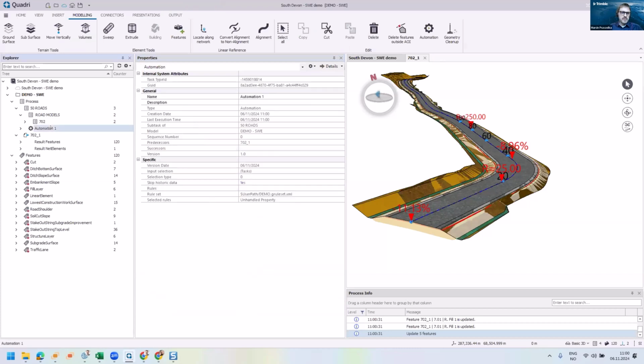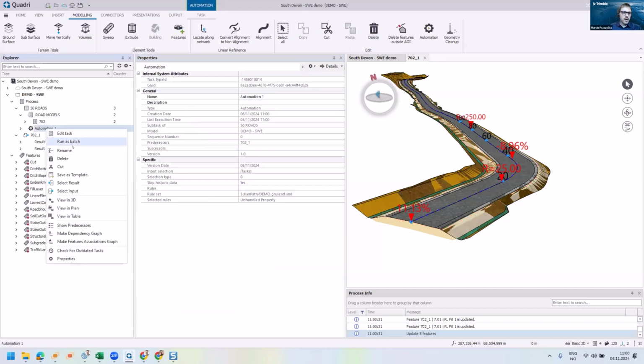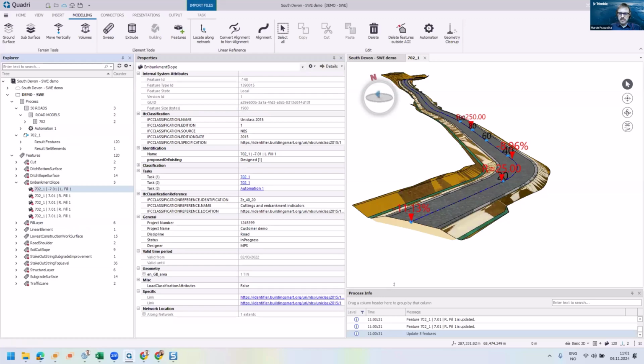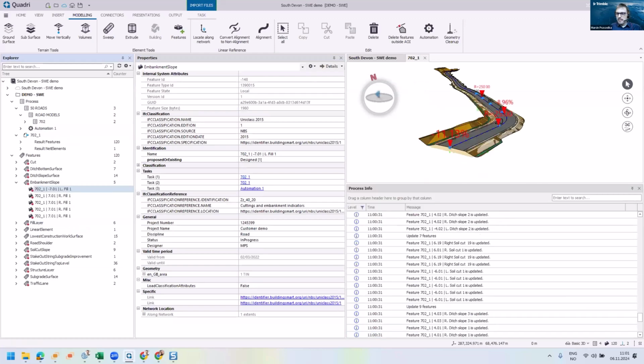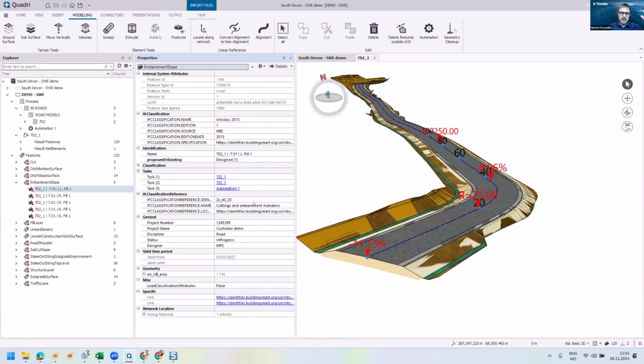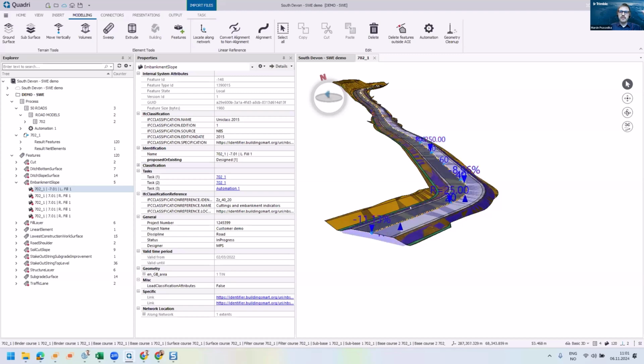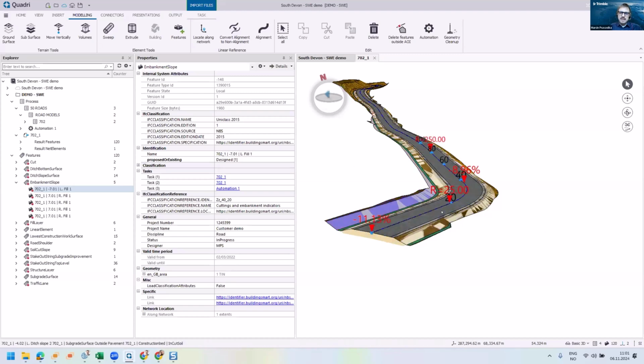I just click finish, because what's nice is that if something happens, you can always run it as a batch. It means that I can automatically update it, and you see that all objects, also the information in this process info, are updated. So I have now all information on my object. So what we can do now, I will still use the same master template to create now my conversion rules, because we have objects, we have BSDD data connected, we have properties connected.